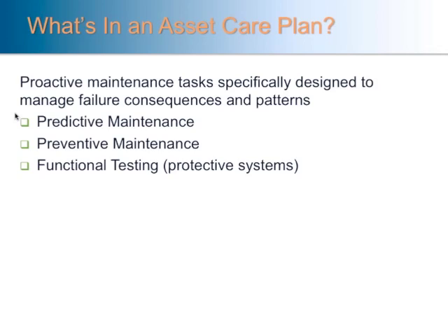That, of course, as we know from the previous slide, is really only technically correct in 11% of the equipment in service. The other 89%, because it does not have an age or a life, must have other methods to manage it, and we see the use of predictive as being one of the tools that has been developed of late to help us in that regard.